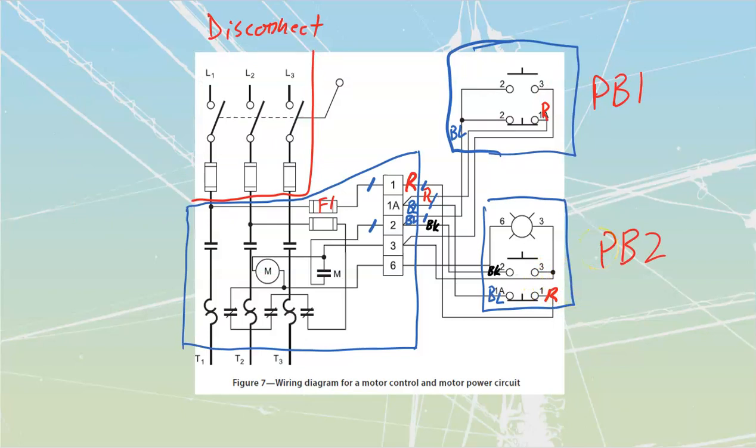Inside of push button number 2, I see that I've got another conductor that is going to go from the opposite side of the push button. I've got a conductor that's going to jump across to a light, and it is going to have another conductor that's going to head out. So all I know is that I've got this thing connecting out to a light and another one that's coming back out. We're going to call that thing the gray. Actually, we'll call that thing yellow. Okay, we'll just call it yellow at this point. So I've got a yellow conductor coming back out.